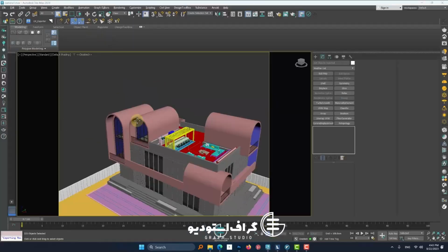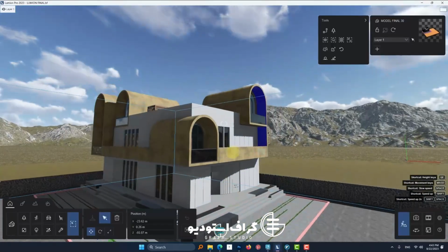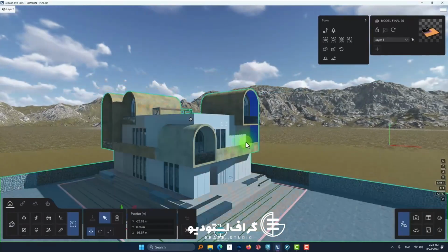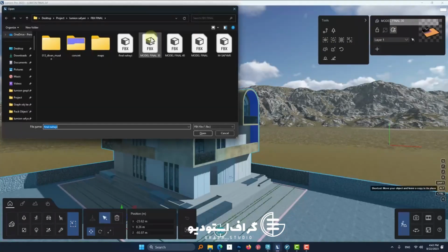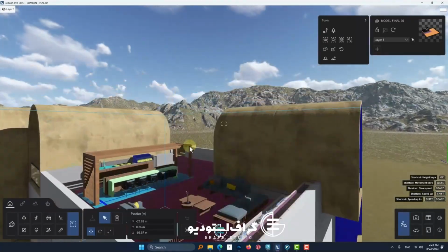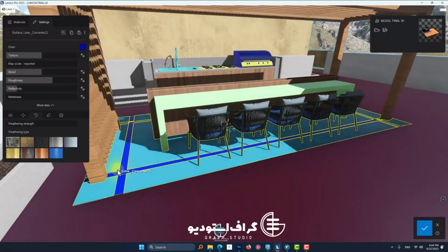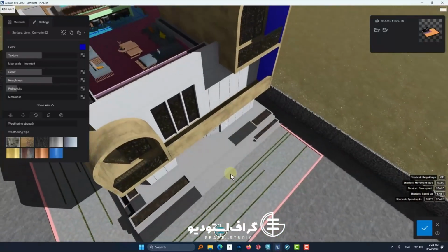In the previous session, we planned to apply the necessary edits to this scene. I solved the issues in 3ds Max in this way. We applied the edits, exported it as an FBX file, and used the model re-import technique. We discussed that to re-import a model after editing it in Lumion, you need to navigate to its specific category or the re-import model icon.